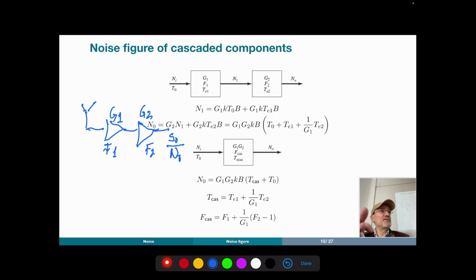The problem is that it's difficult to design amplifiers with a very high gain. So what you usually do is separate the gain over several stages, where it's easier to design those stages, because if the gain is very high, there's quite a high risk that the amplifier starts to oscillate because of possible feedback paths. If the gain is very high, even a small signal gets amplified. The bandwidth will also be smaller, and it's more difficult to design due to the reduced bandwidth. That's why you usually separate the gain into different stages.